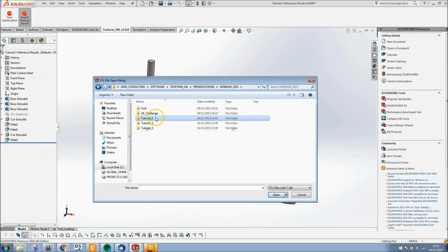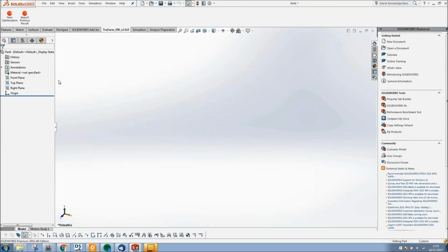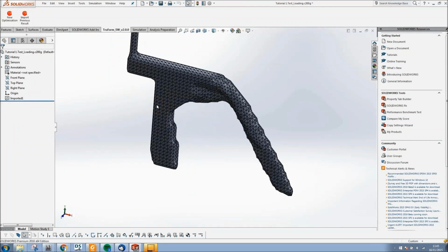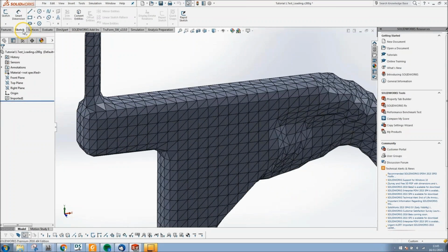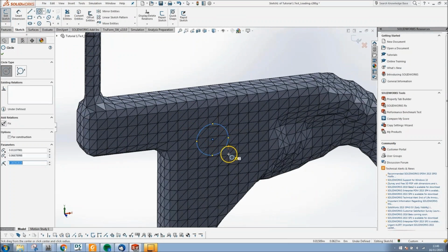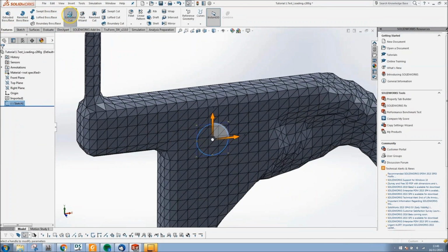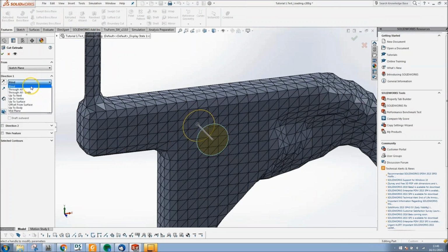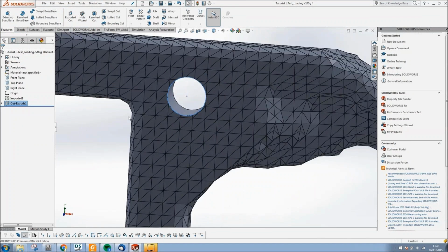And before we conclude this first example, I'll just show you how else you can import the data. So in this case, we'll import the results as a solid body in a new window. And one of the benefits, particularly in SolidWorks 2016, for those that aren't familiar, is you're able to import STL-based body data with more facets, and it works more efficiently than previously in 2015 and 14, if those are the versions you're on. So reasons to update to 16. And you can see here, once we've got the data imported as a body, you can start to manipulate that to make further changes to it, merge it to other parts of your structure, should that be required.